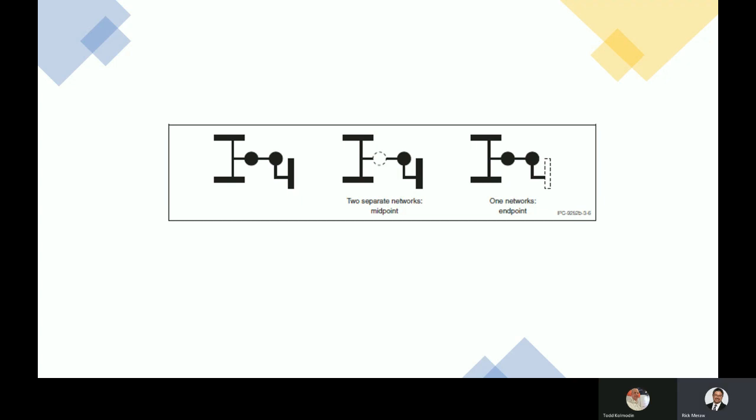Now, that has to be just that, in the middle of a net. It can't be on the end. A would be an endpoint, and C would be an endpoint, because after C there's no other point, or before A there's no other point. So technically speaking, if you had a 3-point net, one trace going straight all the way through, for a couple of the test levels, I think it's A and B, you can remove the midpoint. So you would never need to put a test point on point number B.